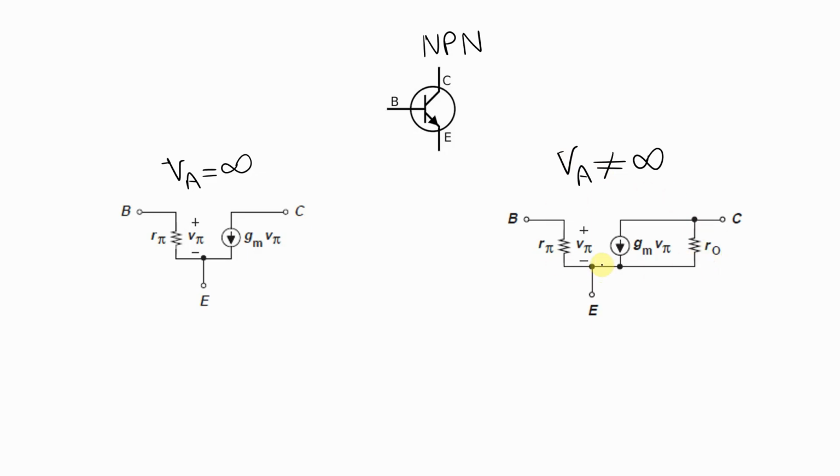And there is an interesting idea which I'm going to use from Razavi's book. Here, this is a PNP transistor, and we're going to use the same small signal model for this transistor, as long as you keep the polarities of this V pi from base to the emitter.